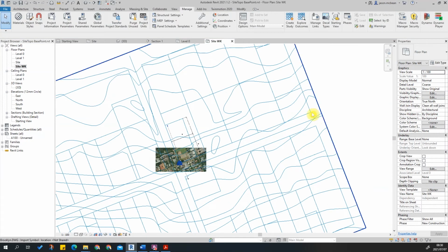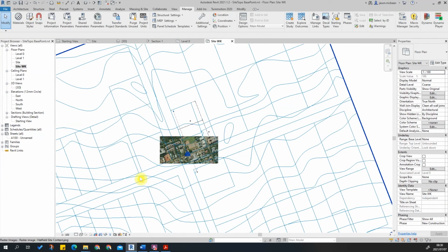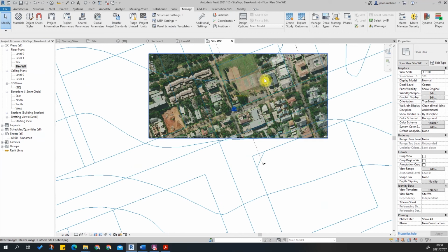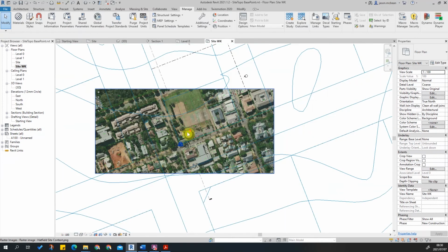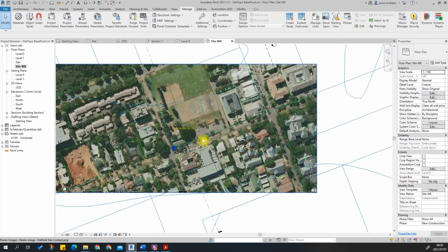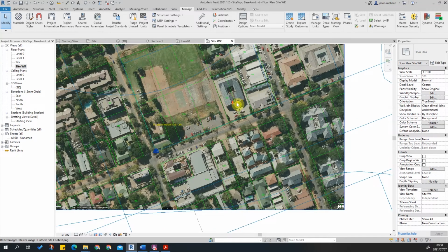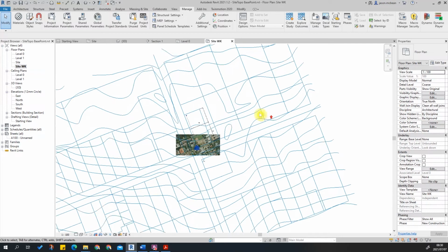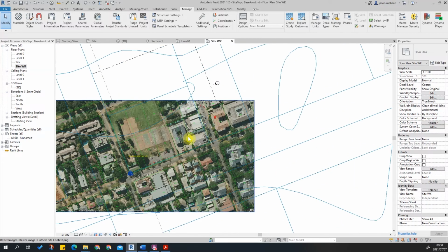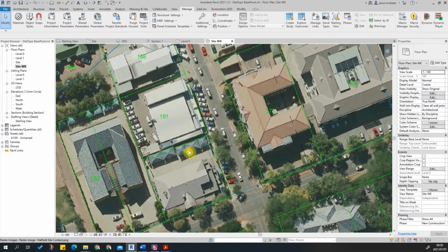And I've got cadastral information in all directions. So in this instance, what I'm going to try and do is I can clearly see how this works. So I'm going to try and scale, I think the road markers over here. So we've got these two narrow sites, 1, 2, and then we've got these two little block sites at the end here, and you can see where they are. So I'm going to use this to scale.